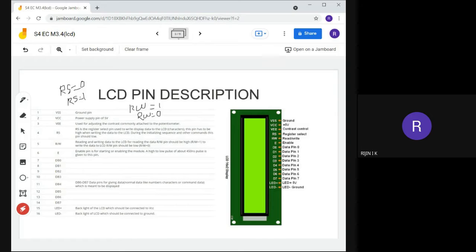Then the remaining 2 pins, 15 and 16, are used for backlight. The 15th pin should be connected to VCC and the 16th pin is connected to ground. So these are the pins present in our 16 by 2 LCD display.